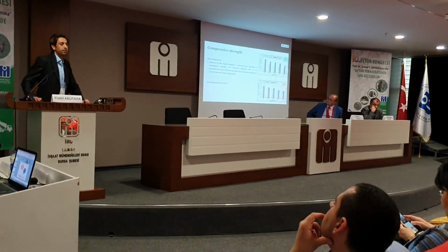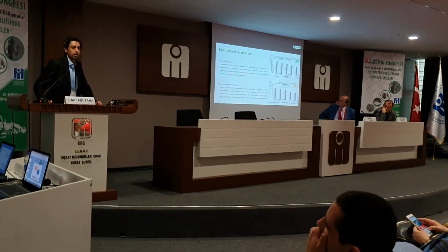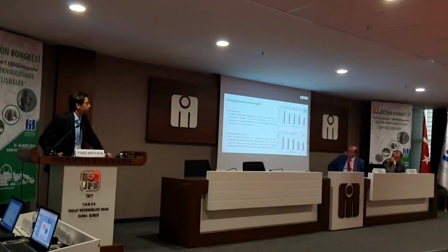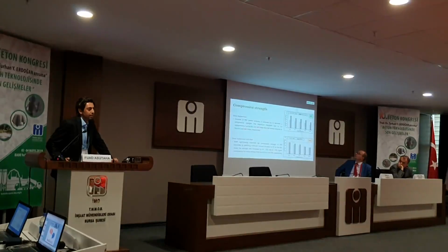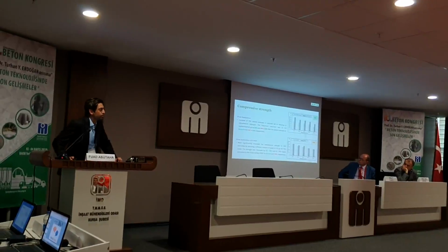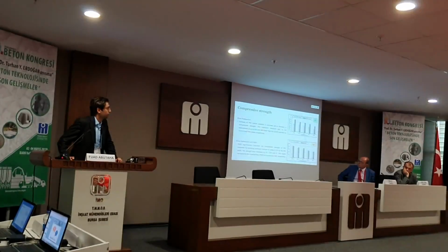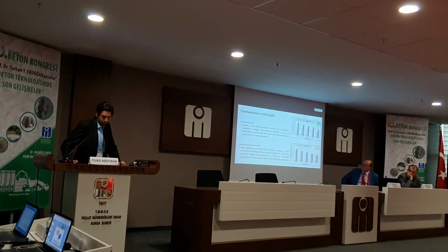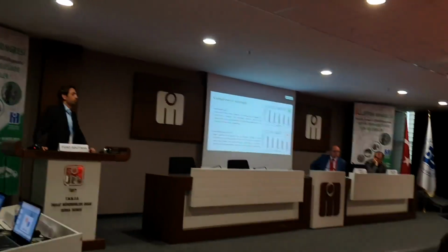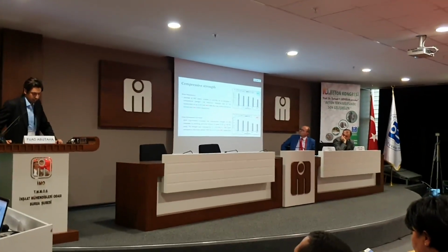But after incorporating the POC powder as filler material to fill up the voids of the POC, we have a significant improvement in the compressive strength compared to the mixes without filler material or without POC powder. The compressive strength increased in the range between 20 to 30% for the normal concrete, and from 0 to 13% for the high strength concrete, compared with the mixes without the POC filler.